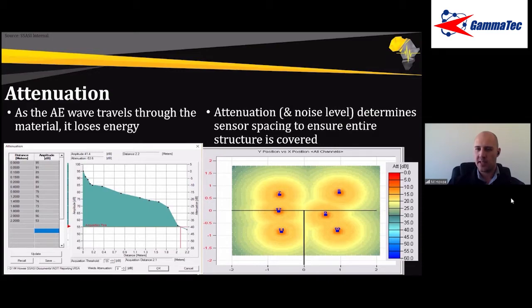So acoustic emission can be used for in-service tanks with product inside. You actually have to have the product inside to evaluate the corrosion. You have to have the product causing the corrosion reaction to pick up the signals to detect it. So the methodology here would be to attach the sensors whilst the product is inside the tank, and then listen for, we need an hour's worth of data, and then grade that accordingly.